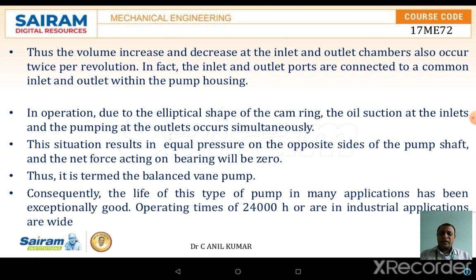The net force acting on the bearing will be zero because of the balanced flow taking place from the inlet and the outlet, which is diagonally opposite. Thus it is termed the balanced vane pump. Consequently, the life of this type of pump is more, and the application has been exponentially good.